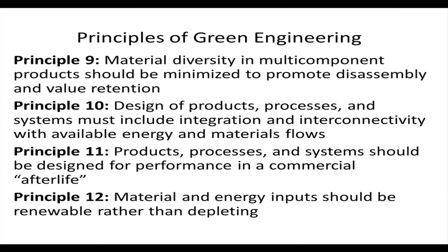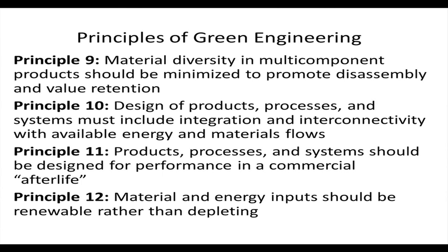Material diversity should be minimized, especially because it goes really against the promotion of recycling or reuse, disassembly and value retention. Many times, just to make things look a little bit cooler, a little bit fancier, we add a lot of materials together, and that really becomes a nuisance for the recycling industry. So what has been proposed in this particular principle is that material diversity, if needed, we cannot avoid, but if not, we should try to avoid so much of it. Within one component, we should have just one type of plastic, rather than 6, 7, 8 types of plastic mixed together as a blended plastic, because that becomes a problem in terms of recycling.